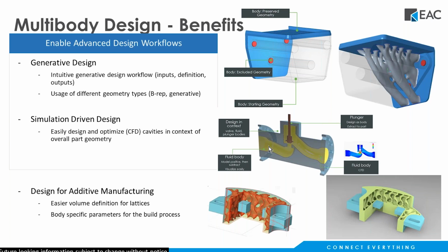So as you can see, it's the way that we have worked with Creo in the past. Usually we would use quilts and things like that to subtract out. In this instance, if you think about quilts, you have to use a lot more features to do quilts. It doesn't help with mass properties, really. This is where bodies will come in and make a big difference.